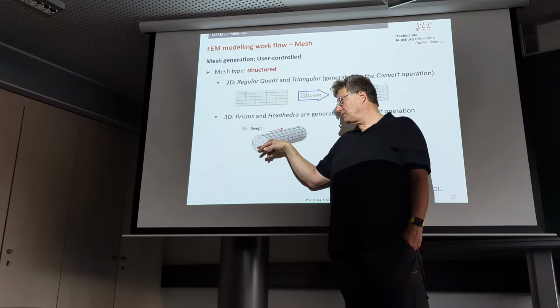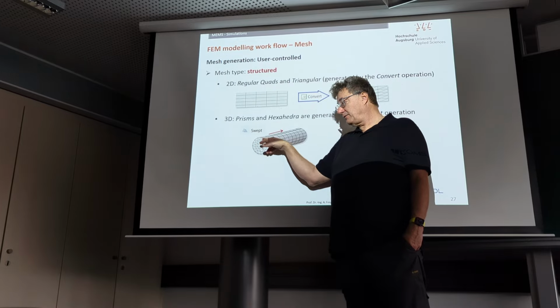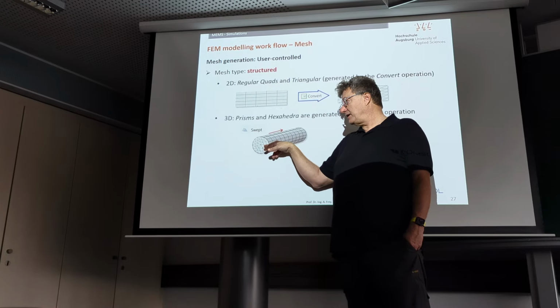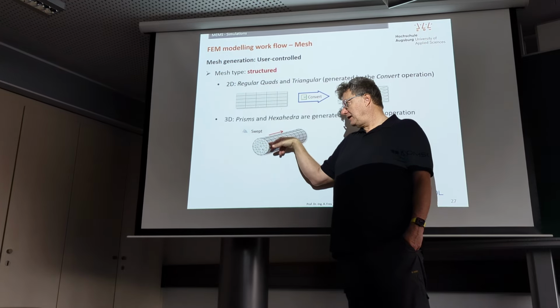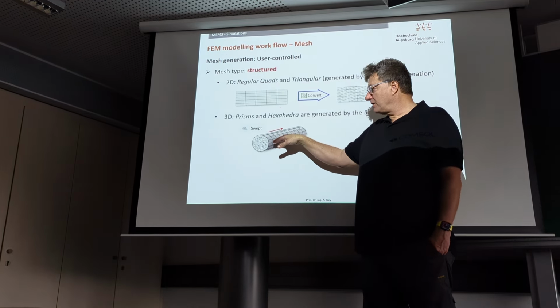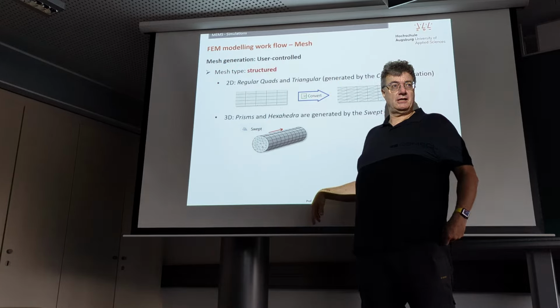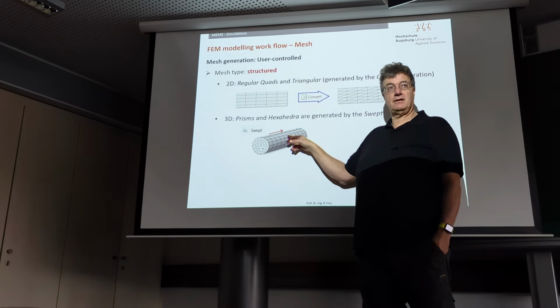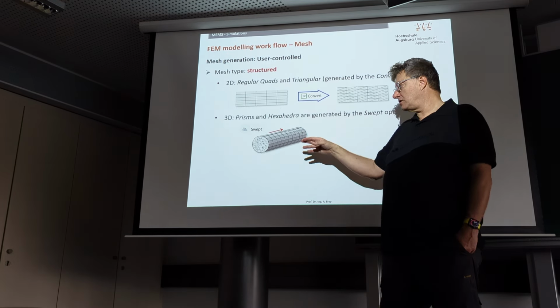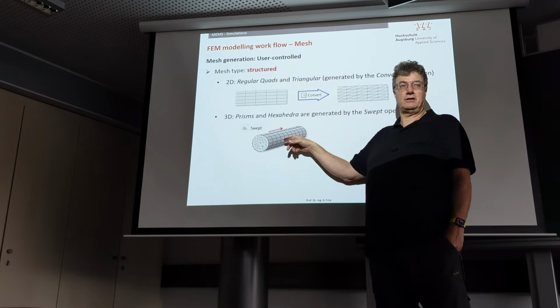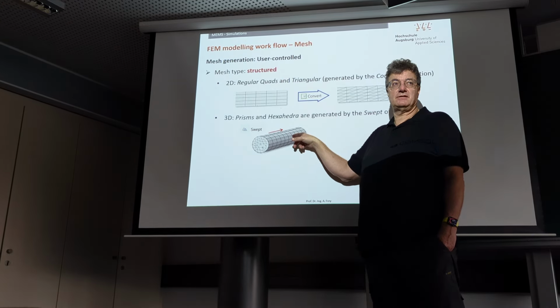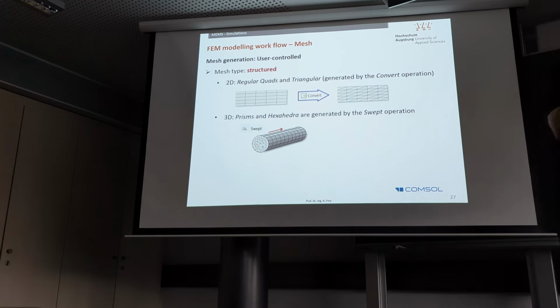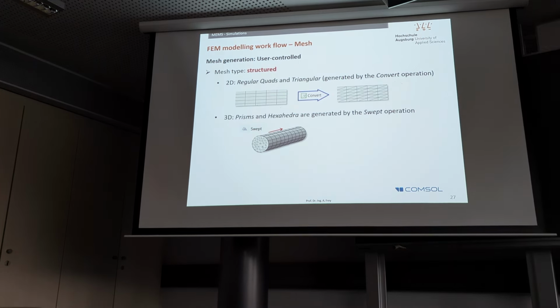You have the highest velocity in the middle. But that, by the way, wouldn't be a good mesh for that situation. But anyway, you should have resolution in that dimension, but the velocity, if it's a long pipe, wouldn't change. You have the same velocity here, then here, then here in that direction. So it's not necessary to make a lot of resolution, because you anyway know the velocity here is the same as there. And ultimately, what would it mean if that would be the full problem I just described? It's not necessary to make a 3D simulation, because there's no information simulating in 3D.